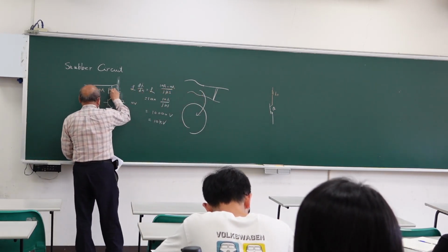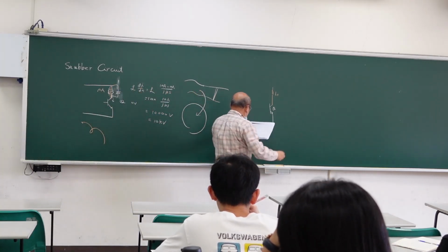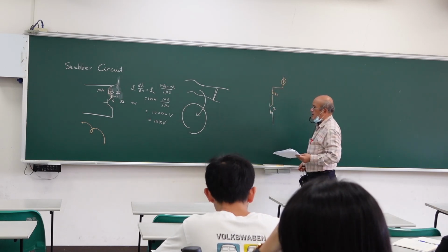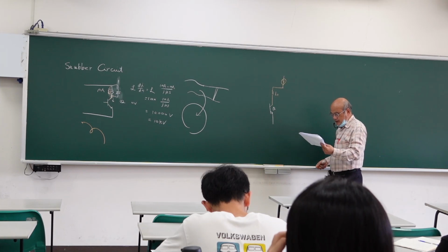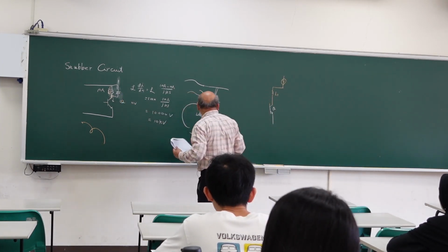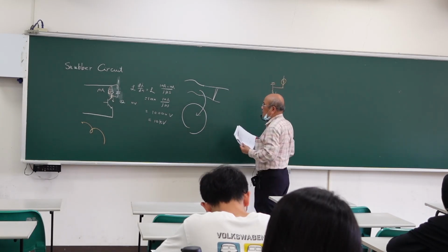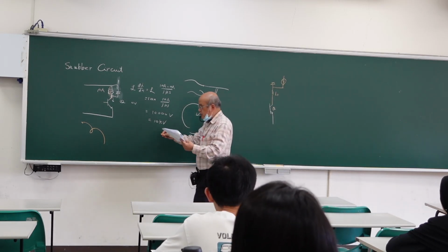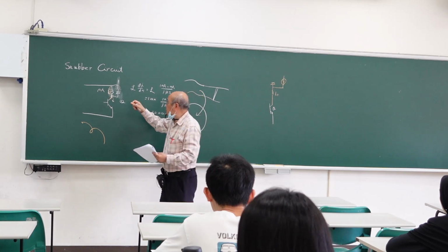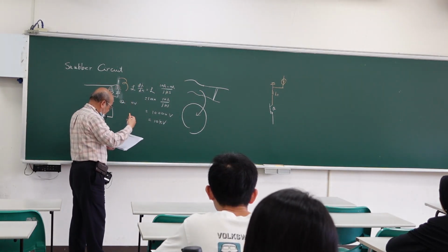This inductor creates constant current, so you have a constant current due to the huge inductance. And then you have a diode here, but for the diode you use a line to connect, and then the line creates a small inductor.